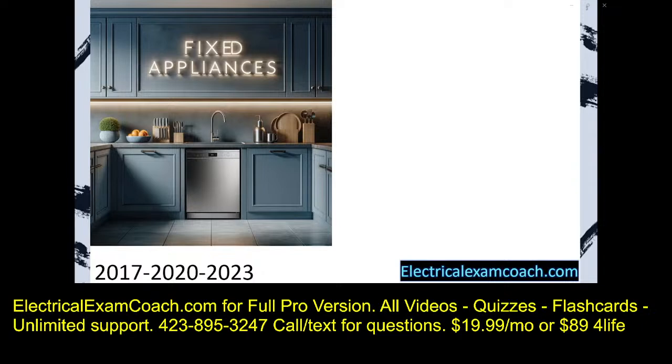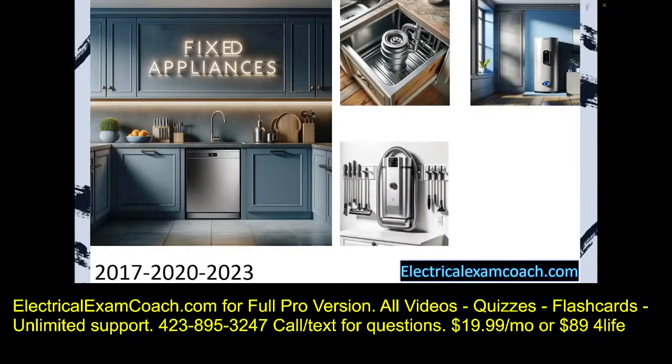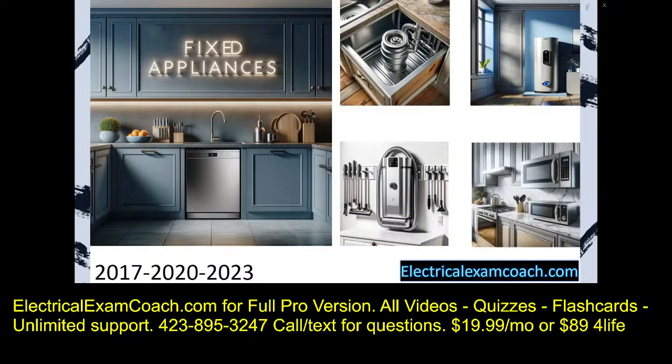Today we're going to be learning about fixed appliances and how they work into a whole house load calculation. Fixed appliances include things like dishwashers in this picture, but it also includes things like garbage disposals, water heaters, central vacuum systems, and microwaves, and pretty much any other appliance once it's fixed. You'll notice in this bottom right-hand picture that there's 2 microwaves. One is not fixed, and the other one is fixed.